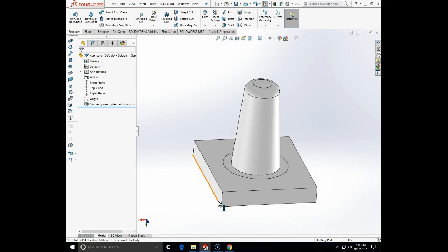Now, those are just kind of the templates of the shape itself. What I will need to do to convert this into a functional mold is to have some way to index these two together, to clamp them together, and a way to bring the material into the cavity, which is the molding void formed between the mold core and cavity. So I will need to create a system of runner and sprue for casting, and I will need some bolts or some other way to keep it together, and I will need some alignment structure, which I'm going to design next.